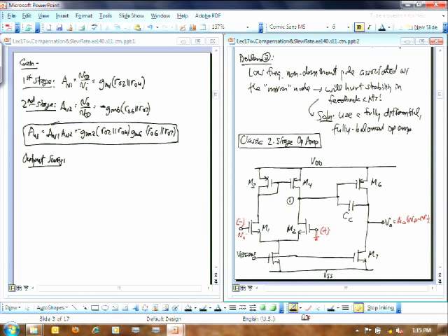That's just going to be VDD minus VSS, which is the total amount of voltage that I have available to swing, but now minus the overdrive voltage of device 6, which I'm putting in absolute values because it's a PMOS device, minus the overdrive voltage of device 7, and that's it. This has a lot of output swing, so it has very good dynamic range. So comparing that telescopic design to this design, this is superior in its output swing and dynamic range abilities.